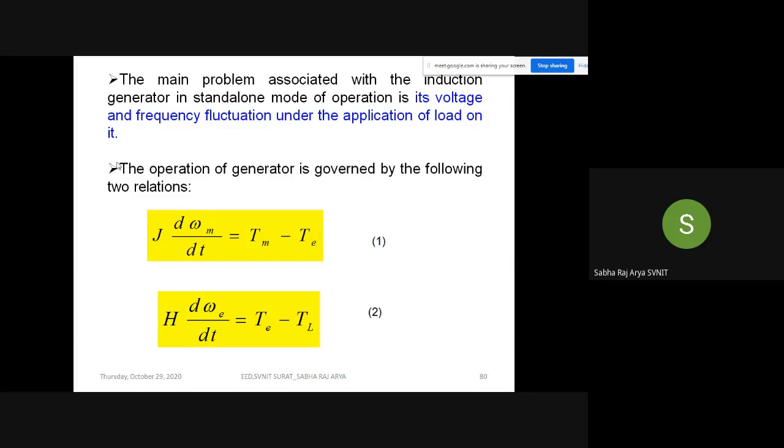If current and voltage are both in the same phase, the supply side converter rating is going to decrease. That is the advantage of an energy storage element, as a battery. If we have the energy storage element as a capacitor, that is also one storage device. In that case, we are not going to inject compensating voltage in phase with the supply current. In that case, the injection voltage is in quadrature with that current. Okay, so those phenomena you can see.